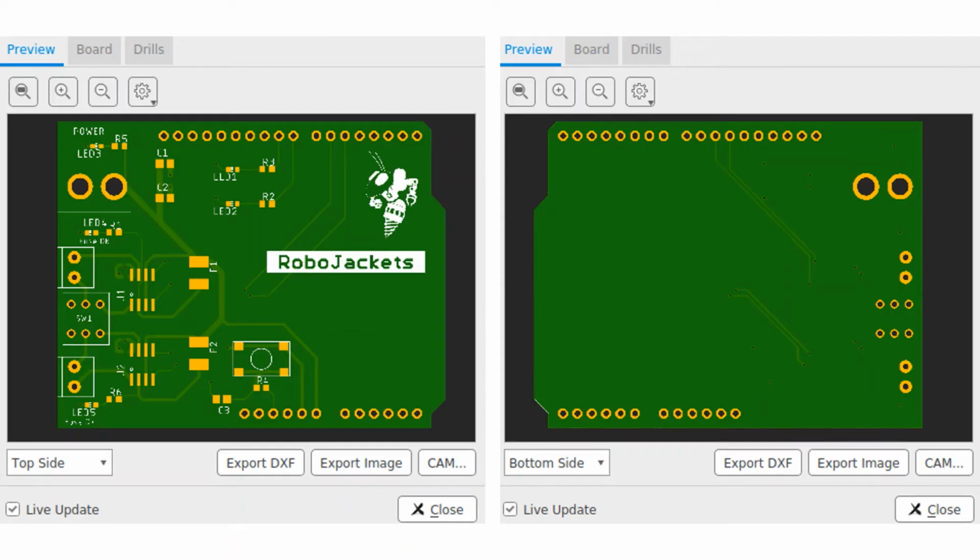The Gerber format is a 2D binary vector image file format. It is the standard file used by PCB industry software to describe the PCB images, like copper layers, solder mask, legend, etc. This is what we will need to upload to the Fab House's website when ordering our PCBs.